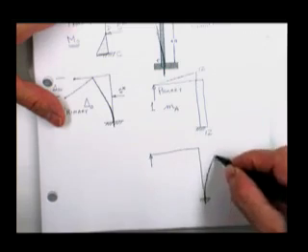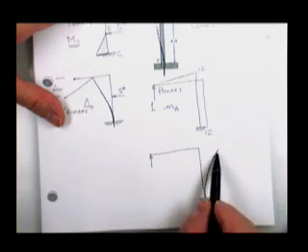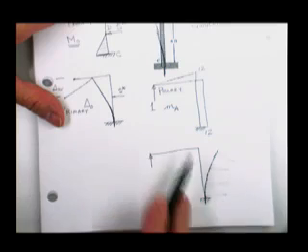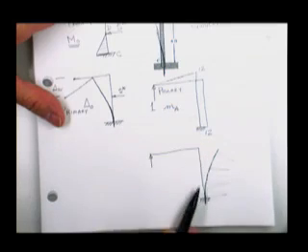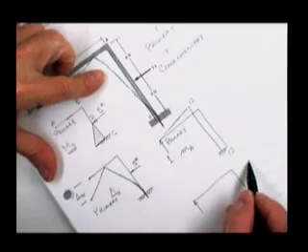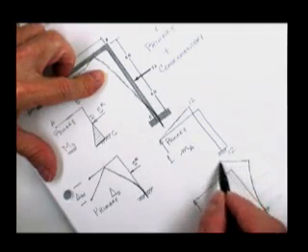That bending right there is constant. In other words, that's rho, that's rho, that's rho, that's the radius of curvature. Has a constant moment, so it has a constant radius of curvature. And then this is a 90-degree angle. It always stays 90, and then it bends up like so.